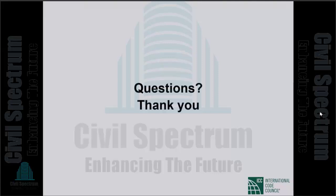ASTM A706 allows grade 550W, that is 80 grade reinforcement. But BNBC 2020 imposes restriction on 80 grade in high seismic zone. Can you kindly explain why? I can easily explain why. It is because BNBC is based on old codes and specifications.